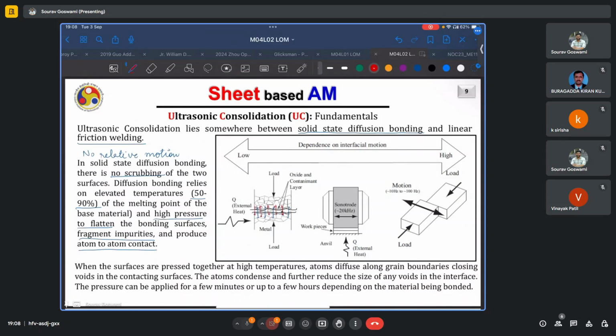However, atomic diffusion occurs at very small length scales, so they must be brought in close contact. Secondly, if the surface is dirty, the diffusion process might be hindered, so you have to clean the surfaces. Again, you need high temperatures to energize the atoms for such diffusion to take place. In the ground state, they will not want to diffuse across the interface because there is no driving energy.